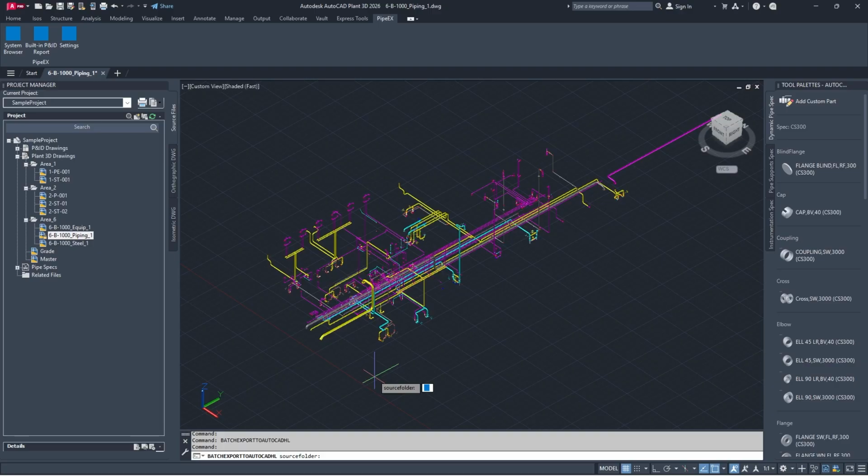And it changes things a bit, because technically you can even execute those commands with PowerShell, or you can fully automate it. So you can create a script that will first open the Plant 3D project, then load this DLL file, and then execute the command. If you're lucky enough, then in your company it's allowed to use task scheduler, but in most cases, unfortunately, it's not possible. And that's why you always need to use the manual way.